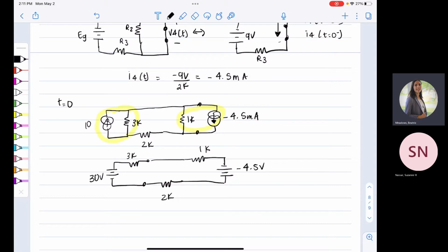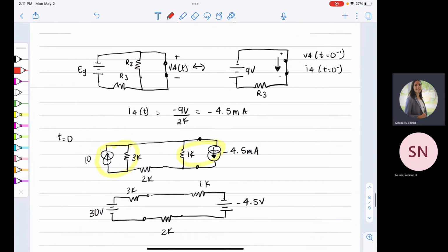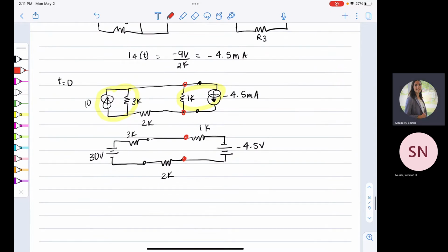Okay, and remember the voltage we're trying to find is the voltage across the inductor, which is the same as the voltage across the R, right? Because they're in parallel. So it's still that voltage here, right? Does that make sense to everyone? Okay. Because that would have tricked me on the test. I would have probably ignored that and said, oh, it's 4.5, but it's not. It's the voltage across all these branches now, since it's the same as the voltage across here.